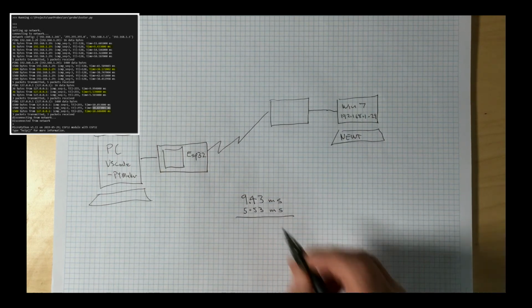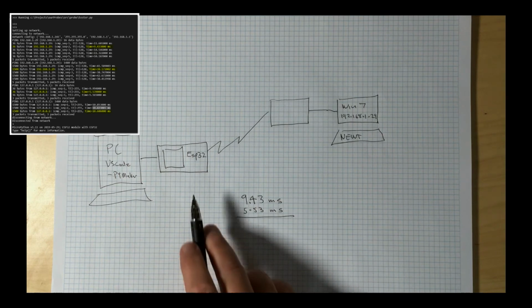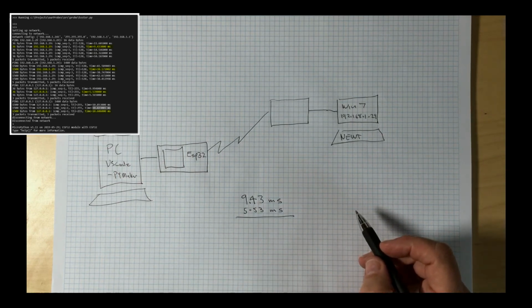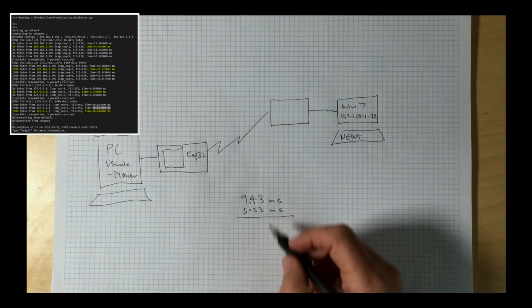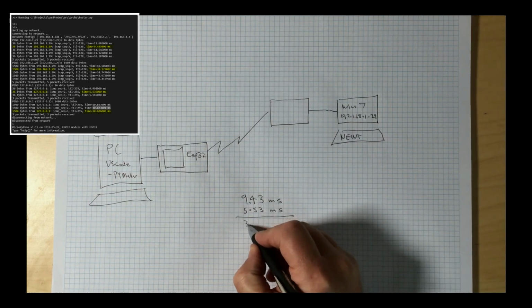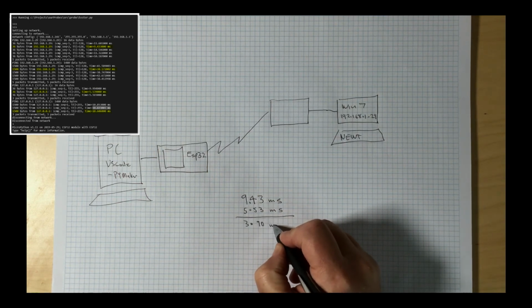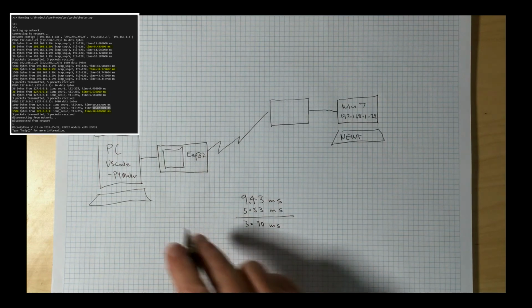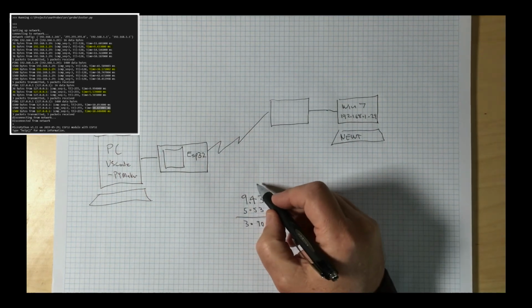I did that second one just to get a baseline, because there's a certain amount of time the esp32 ping routine takes to load buffers and do things on the actual processor before it sends things across the network. By taking that out of the picture, it gives me a better baseline for what the actual time was on the network, not including esp32 processing time.